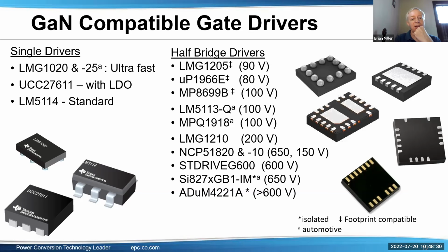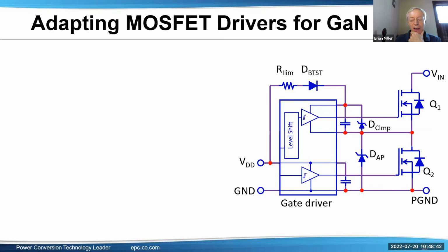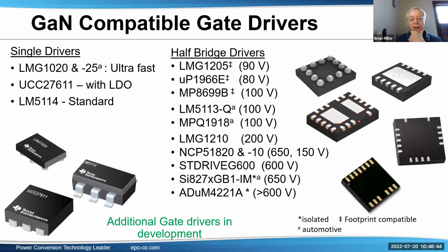Current sense transformer in the half bridge. I don't really know. It can be, if you have a favorite place to put it with the silicon MOSFETs, because of the array of gate drivers now, you might be able to do the same thing. In other words, if you prefer a gate current transformer or current sense resistor in the bottom, there are ways to isolate that from the bottom gate drive loop.